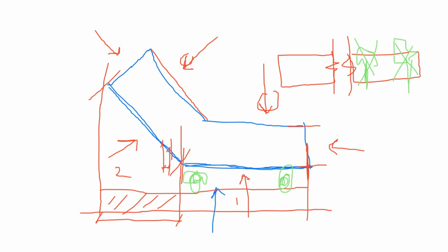And let me just flip back here. So these are the two notes that we apply in elevations and in sections as well. If you do have a building and you are making a section in it, you do not draw your section continuously like this, because anything else you would see outside the rigid element, or the 90-degree vertical horizontal thing, will be projected, and that is what we want to avoid. So instead, you will cut and make another section here, so that your section shows logically what needs to be shown in your building, to avoid having any inclination as well.